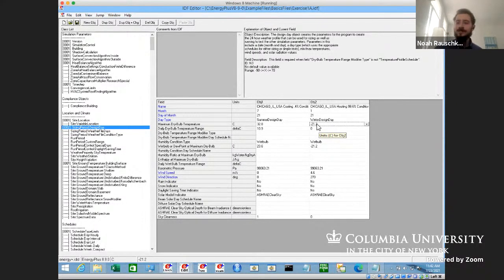For winter design days, the way that EnergyPlus and the whole field operates is you do what's called a steady state heat loss problem. You just say minus 21 constantly. What kind of heating system do we need to keep up with just that steady state, frigid cold temperature continuously? With the summer design day, the standard is to still solve a transient problem where it is heating up and then cools back down, and you just need to keep up with that cycle.